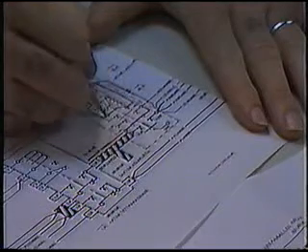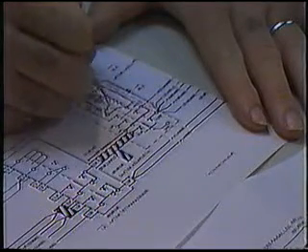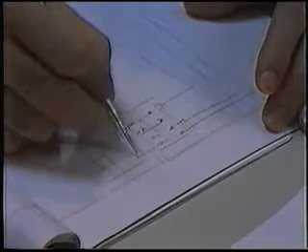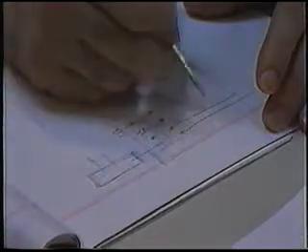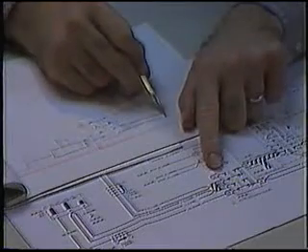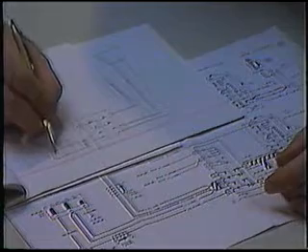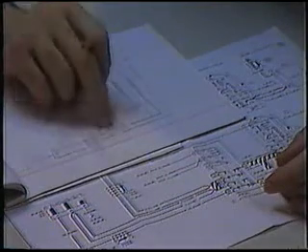This will lift out only the circuit affected. Another suggestion is to redraw the segment in question on a scratch paper, omitting surrounding wiring. Now, using simple logic and common sense, isolate and check until the defective part is found. Then repair or replace as necessary.